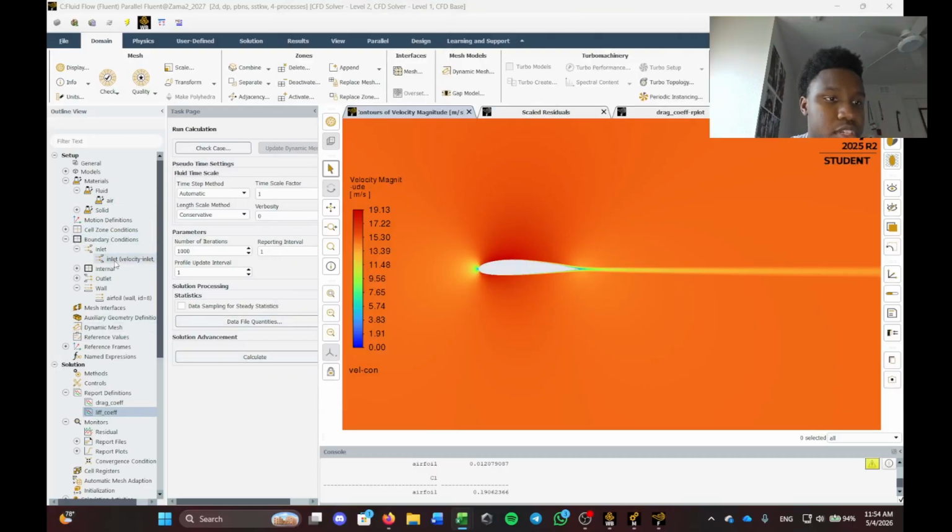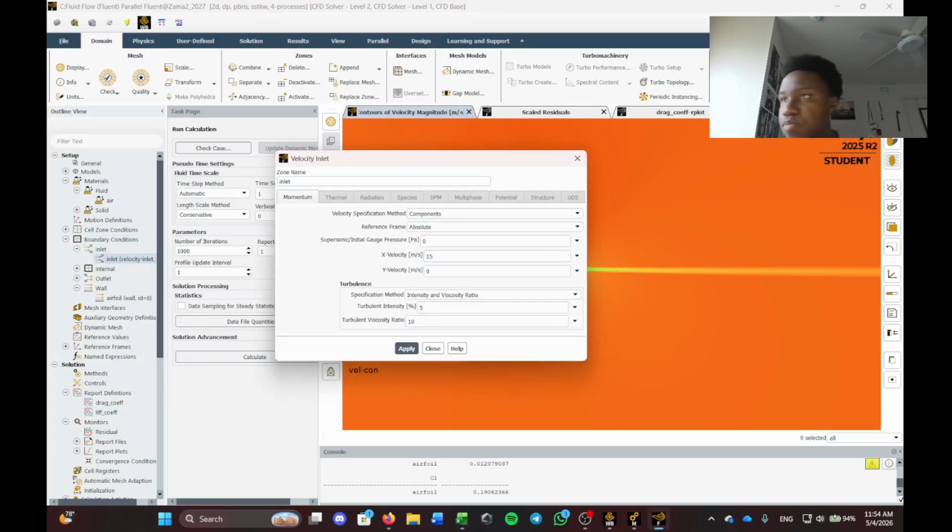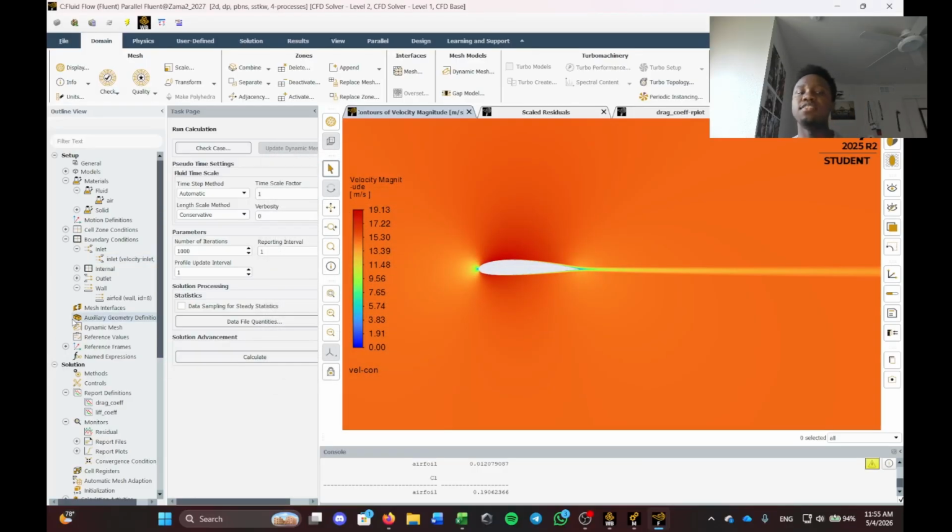But first thing I'm going to change is the inlet velocity here for our simulation. So like I said, for 10 degrees angle of attack, 15 cosine 10, boom, 15 sine 10 degrees, get this guy here, apply that, and then you'll actually see in the simulation that one stagnation point, you'll see it move, which makes sense as we change our angle of attack.